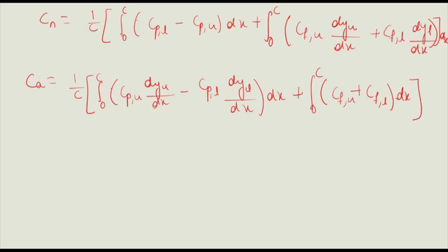Now, we have here the integral forms of force and moment equations. Okay, so if we are considering an inviscid flow, as we said, the drag is 0. The drag is assumed to be 0 in case of an inviscid flow. So when I say inviscid flow, Cf, which is the coefficient of drag, becomes 0 over here.